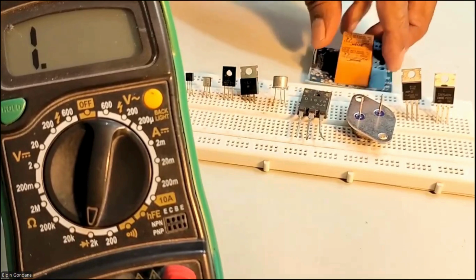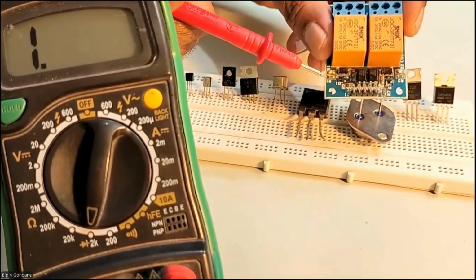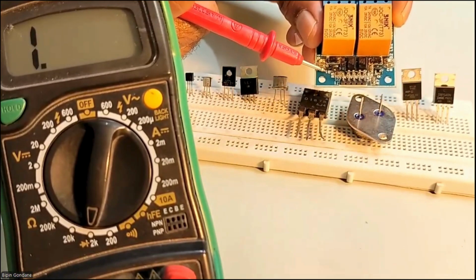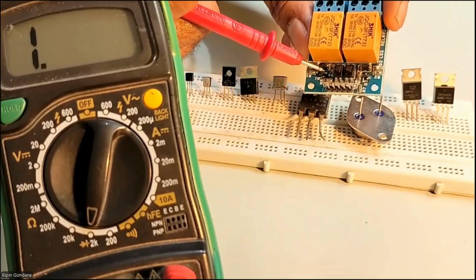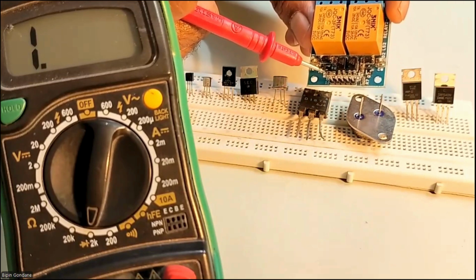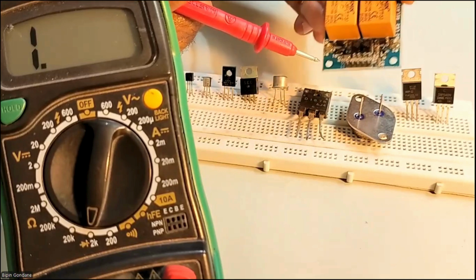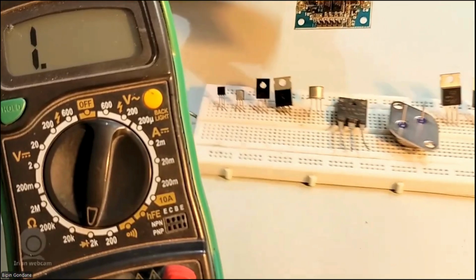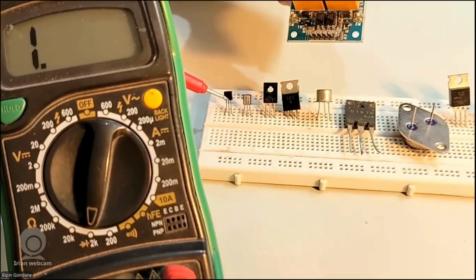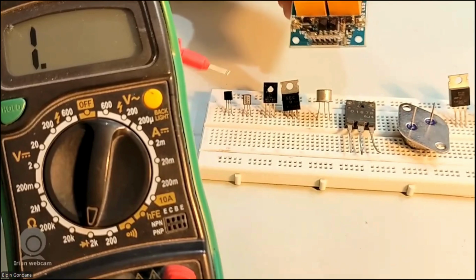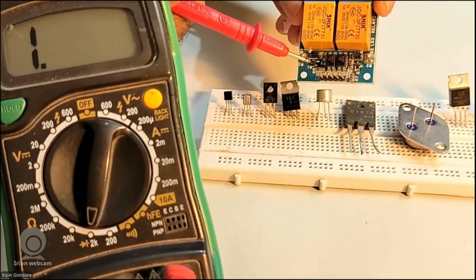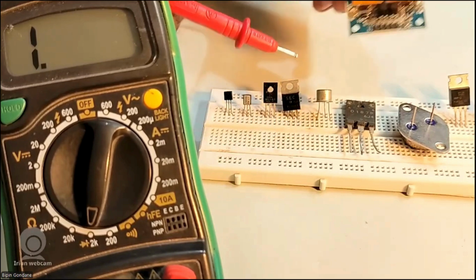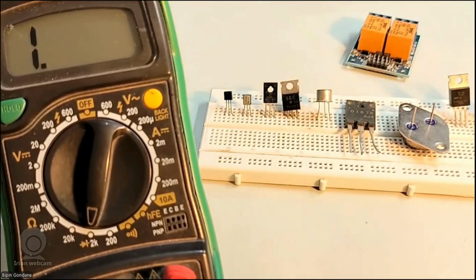So you can see in this, I told you this is small. Even this transistor we can test, but it will be a little difficult. The side is base. The top one is collector and this side is emitter. So the transistor which we see here, this is BC547, right? A BJT transistor, the same BJT transistor in a different package. So likewise, we can test this. These are very, very basic things that you should understand.